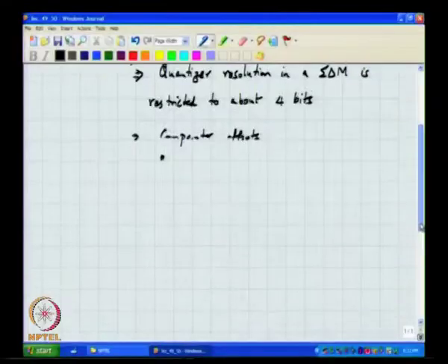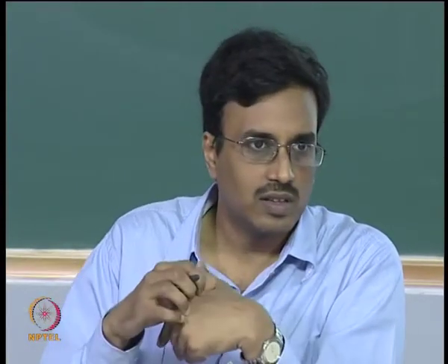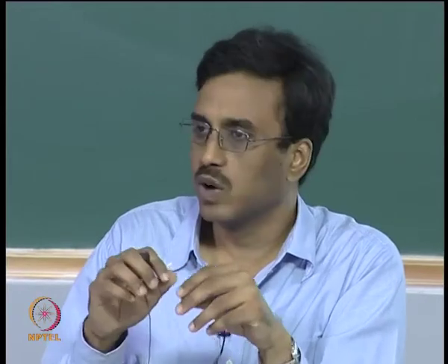So, a DNL and INL problem is usually not an issue in a delta sigma loop, simply because nonlinearity only causes the quantization noise floor to rise, okay. I mean, so if you take a standalone quantizer, the ideal spectral density is delta square by 12 divided by Fs by 2, that is the noise spectral density of the quantization noise.